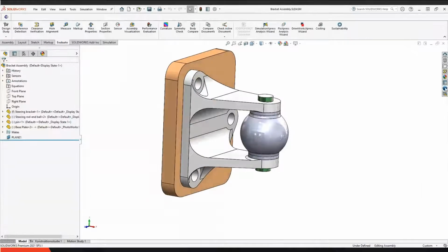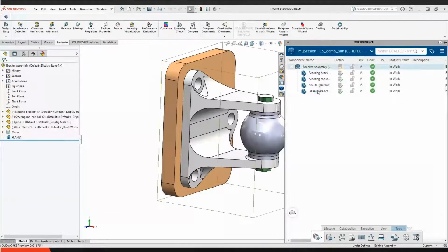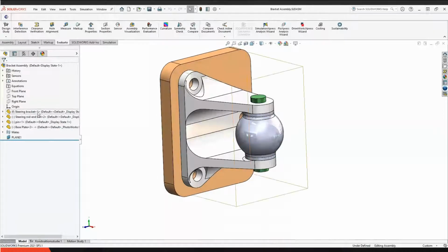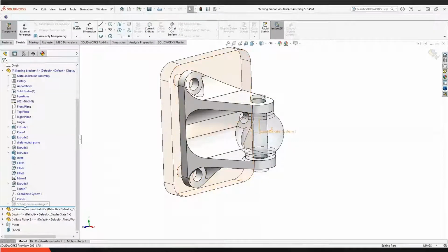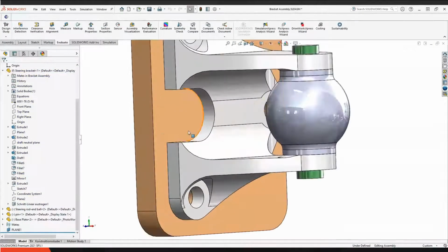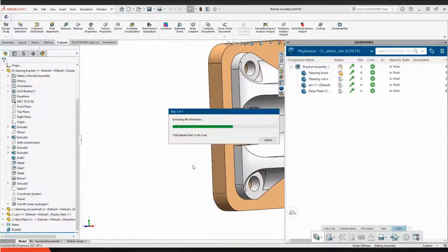And then we want to make a change. So we go to the part, and this is really cool. This is the PLM system built into SOLIDWORKS. So you reserve the part, the whole assembly, so now you can make changes, and it can actually keep the changes instead of being read-only. So you go and make a cut in the part or whatever you might do. It depends on you. And then you would go back and save all the parts.